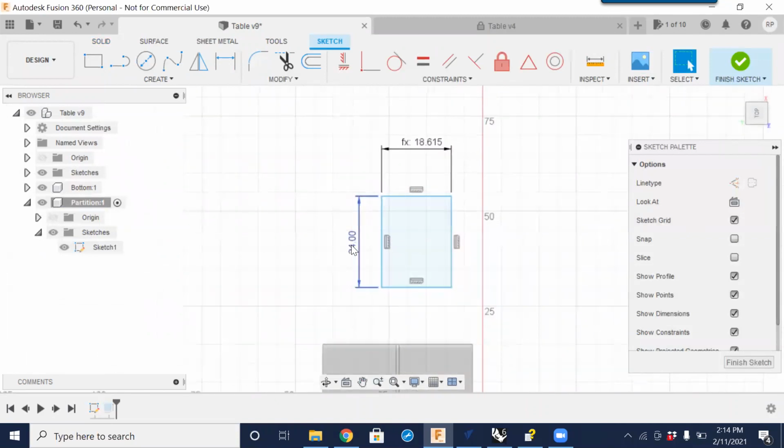I'm going to double click on the 24 to allow us to change this number. So I could change it to a 30 if I wanted to. I mean, that is just awesome that it's that easy to change the size of a rectangle. But if we want to control that much easier using that user variable that we just created, you know, right